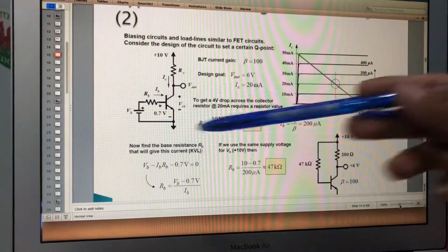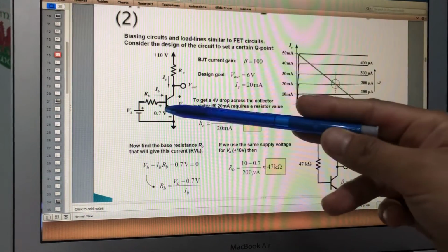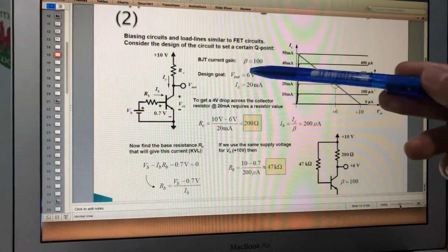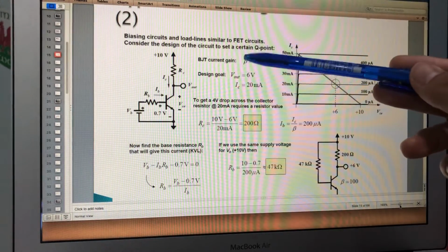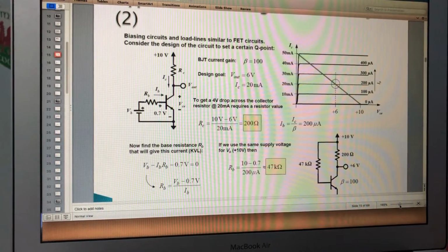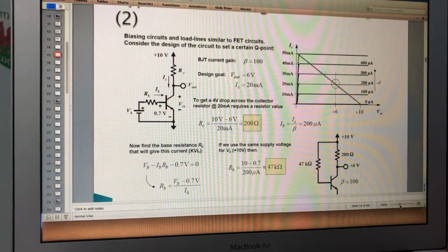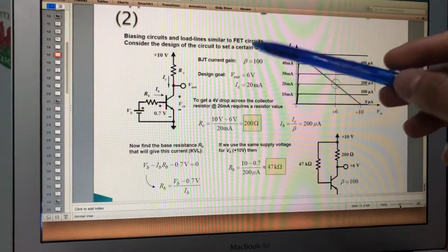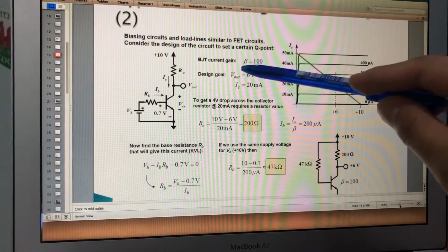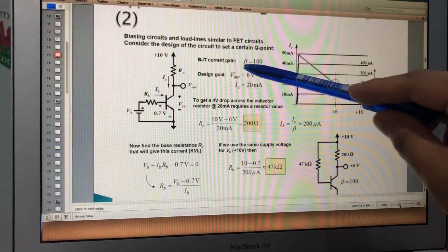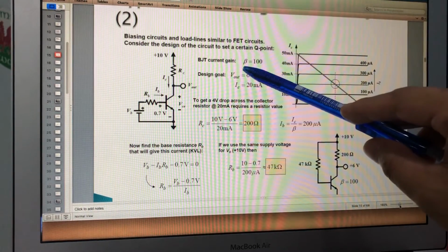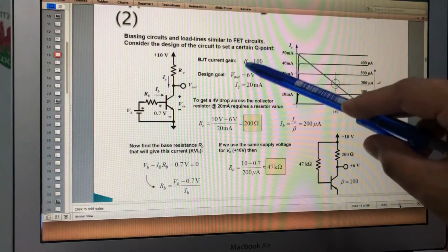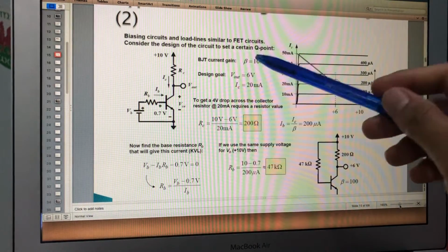When we buy the transistor, it comes with a data sheet. In the data sheet, it has the beta values. Beta values also can vary. Sometimes they have min and max. In some of my courses before, I showed you the data sheet. Sometimes they call it beta; for power electronics, it's called HFE. So this is the beta value.